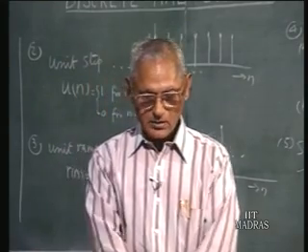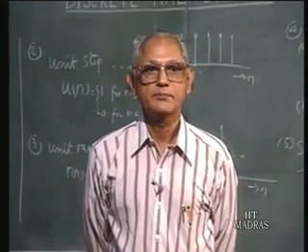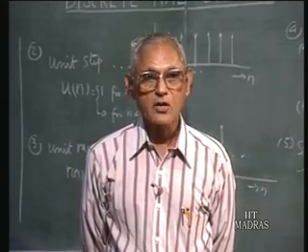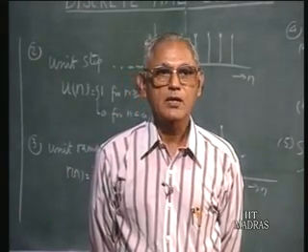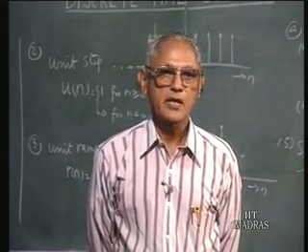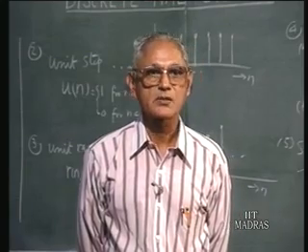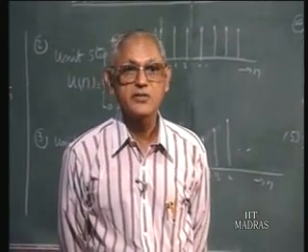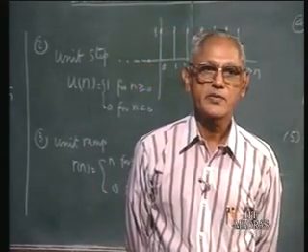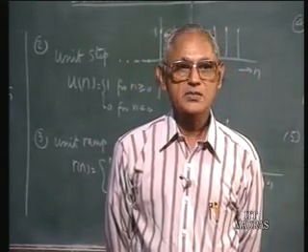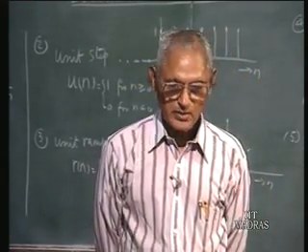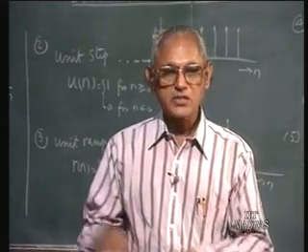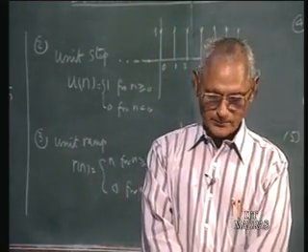We talked about the linearity property, the time invariance property, and the causality property, and we will confine our discussion to linear, time invariant, causal discrete time systems. These are characterized by a difference equation of order n in general, where the order of a difference equation is the difference between the highest argument and the lowest argument associated with the dependent variable.